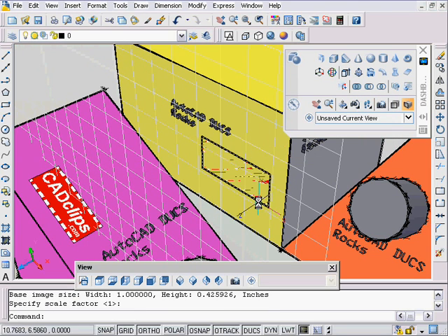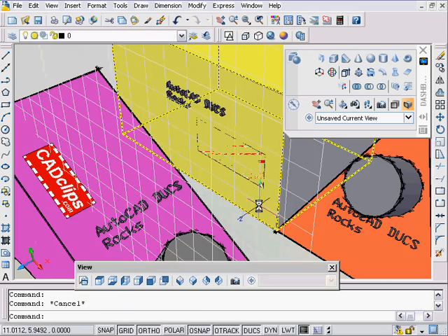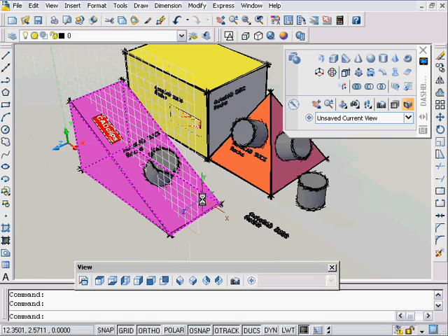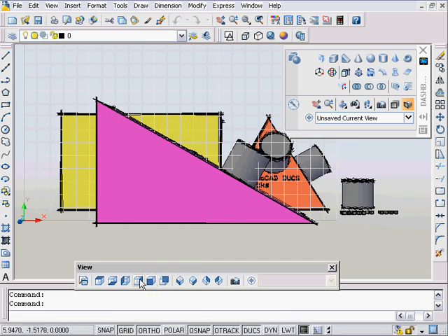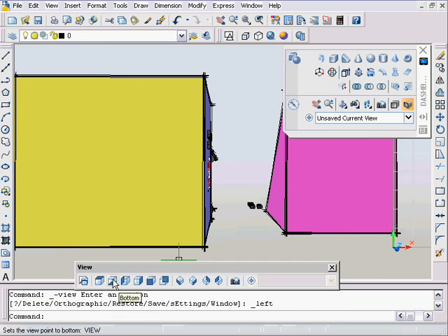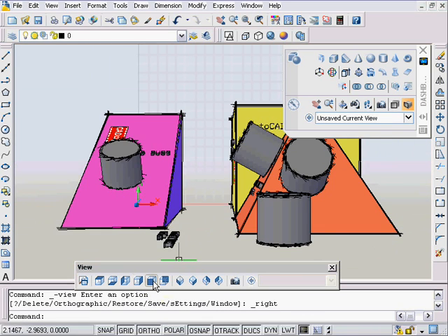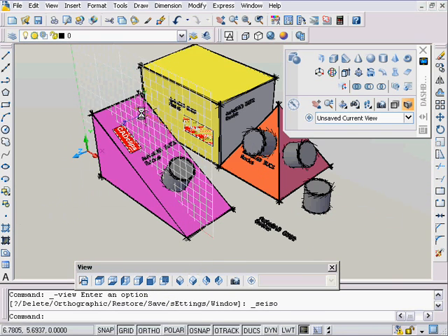Okay, insert, same thing, different surface, place it on over here, you know, for your billboard effect, and then take that and move that off of that surface if you want it to show. Okay, you can see right now my grid is showing my UCS is pointing vertical, and that's because when you switch to be these side views, it changes your UCS to be perpendicular to that. And then when you go back to your 3D view, you're left with that last one.